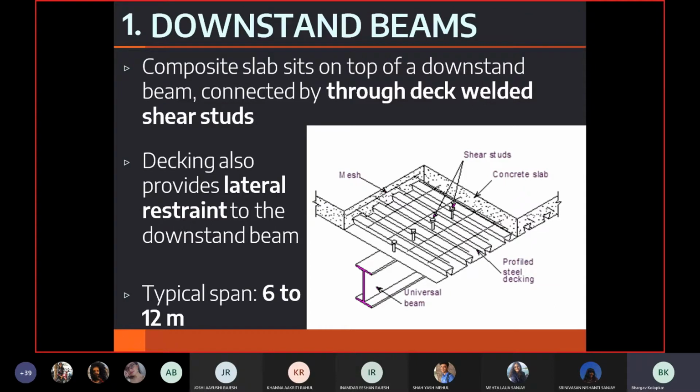Now, if we go back to Theory of Structures 5 and Design of Steel Beams, there was a phenomenon that the beam was susceptible to, which is called lateral torsional buckling. What we said there is, in case there's no lateral restraint to the beam, the top flange is under compression, the bottom flange is under tension, and steel has a tendency to buckle. So the top flange, which is under compression, tries to buckle, but the bottom flange is in tension and does not let it buckle. Then the compression flange deflects, and there's a moment and torsion at the same time.